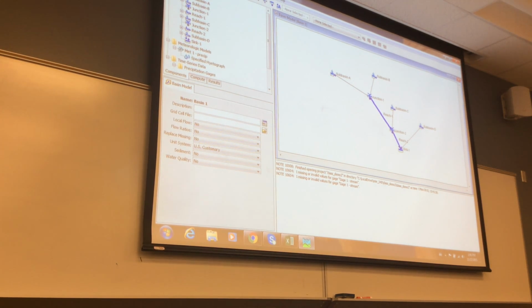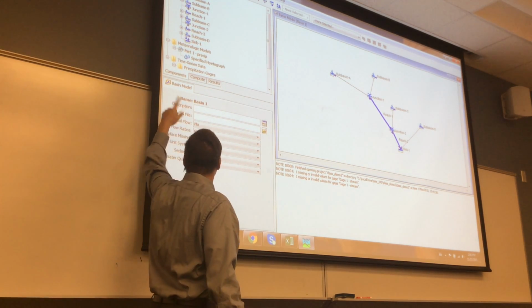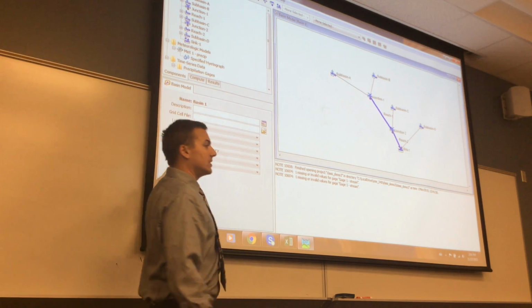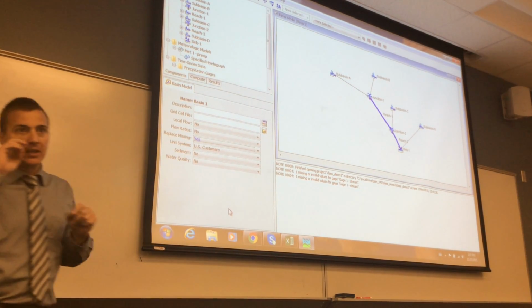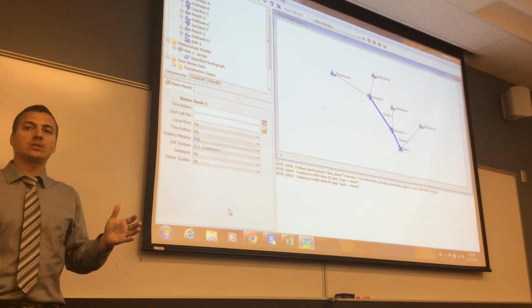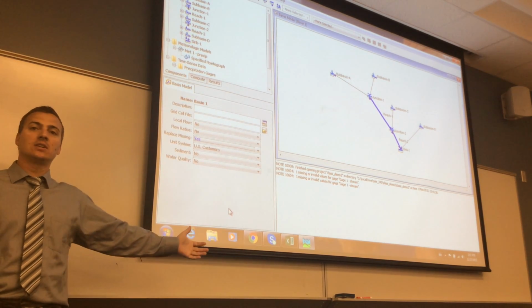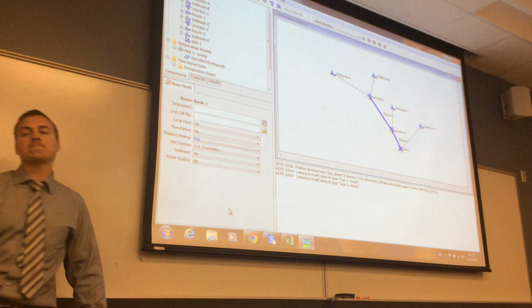I'm gonna change one more thing, but I think this is because I have an older version. I click on my basin. At my basin, I'm gonna say replace missing yes. I don't think you need to do that in the new version, but it is what it is. What does a replacement mean? It means if you have missing values, like our precipitation only goes for 14 hours, and if we want to run it for 5 days, it would just put zero hours. Zero.